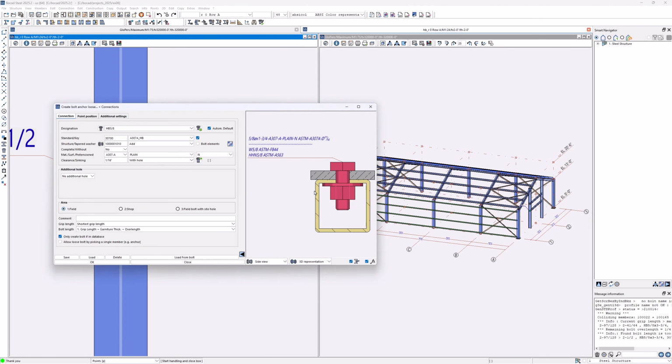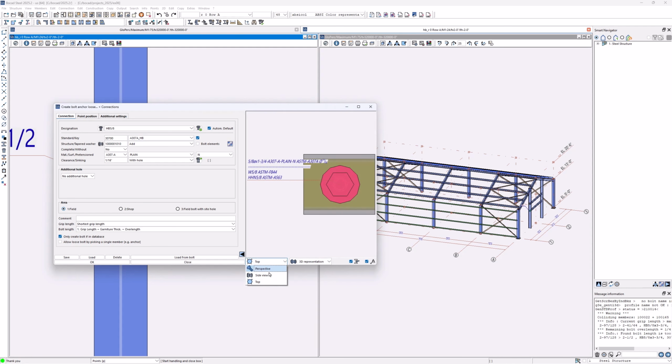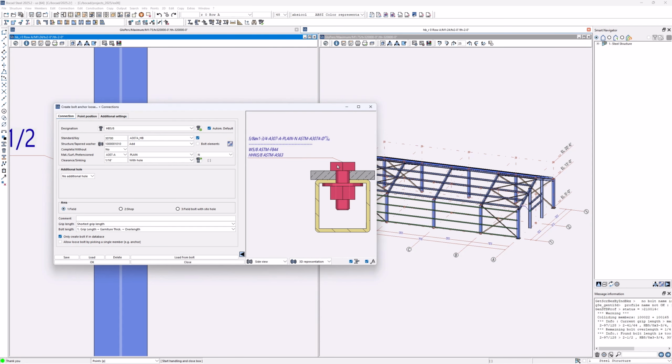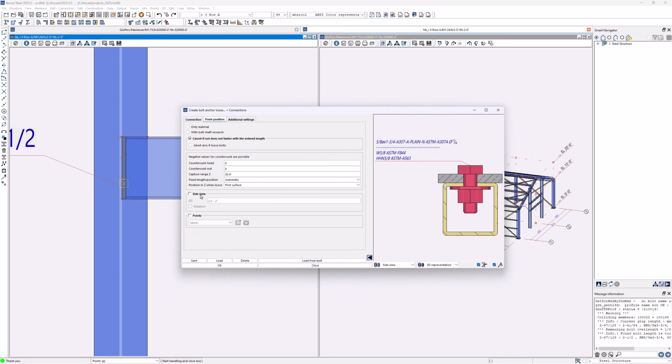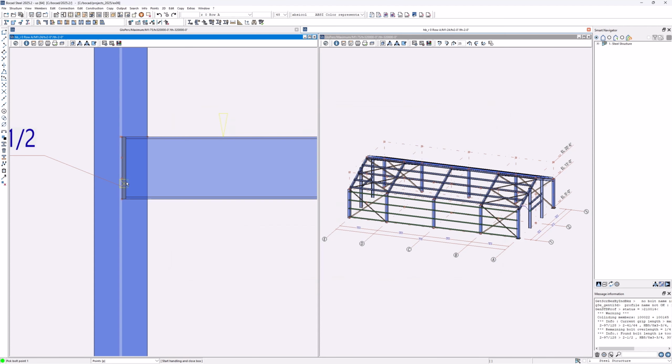The idea of creating bolts is just like the holes. We're creating them in front view. So we're looking at the head of the bolt, not the side view as what we're having here. We're basically looking at it like this from top. So if I want to create a bolt in side view, we can still do that, but I have to go through the second tab, side view, and specify an offset. So here it says absolute or running dimension, 2 inches in front, 2 inches behind from the axis. So let's see, 1, 2, enter, and these components are to be connected.